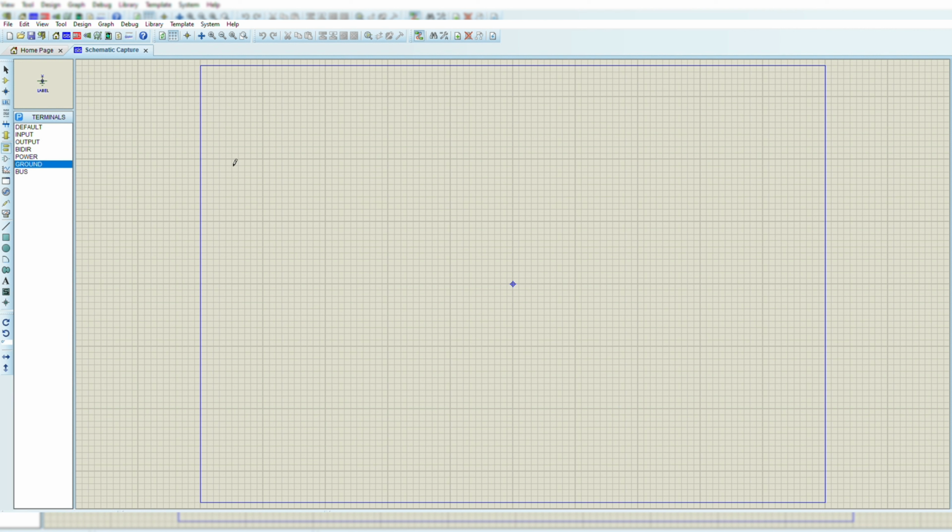So we can go to the quick example, where we are interfacing an LED with the 8051 microcontroller. To place the components, we need to use right click, that means right click in the PCB area or the simulation area. This is the simulation area where we need to place the components.